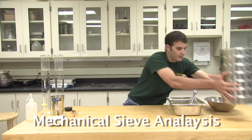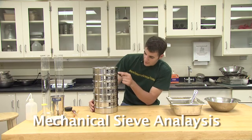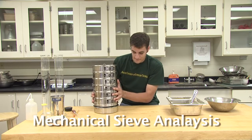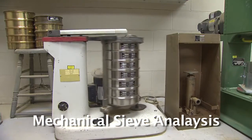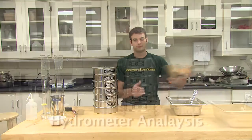The devices required in order to conduct a mechanical sieve analysis are a stack of sieves ranging from number 4 to number 200: 4, 10, 20, 40, 100, 200, the pan, and a lid. A mechanical shaker, a digital balance, and a weighing bowl.